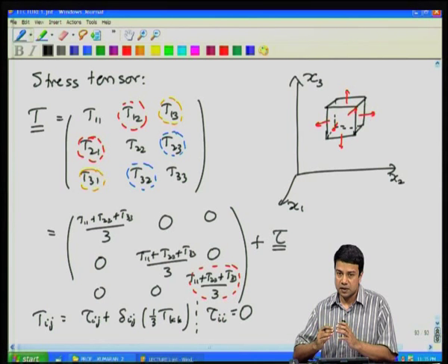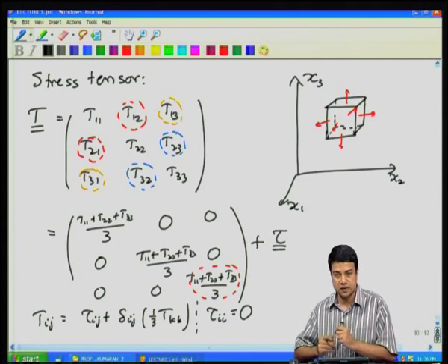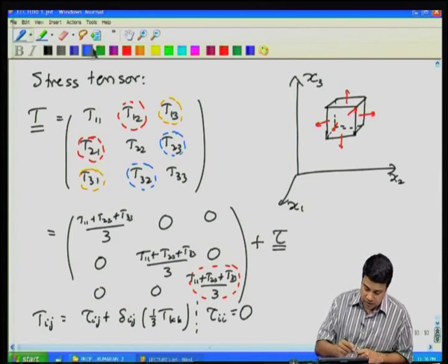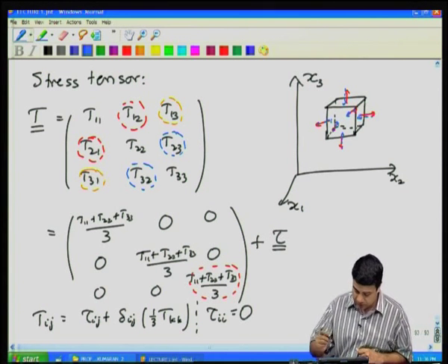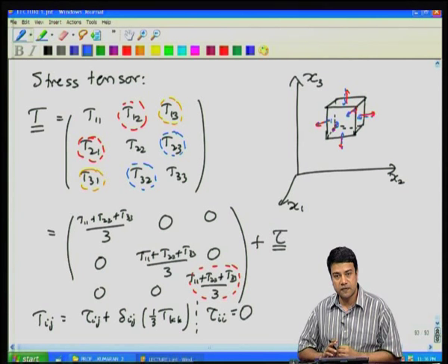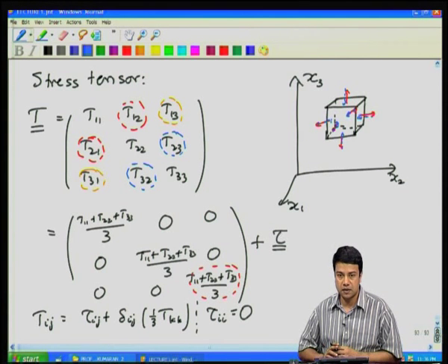At each point, okay, if you have a surface to measure that hydrostatic pressure, the force always acts perpendicular to that surface. Okay. So, the pressure is defined as a force that acts inward at each location, okay. Whereas, we have defined our forces as acting outward.